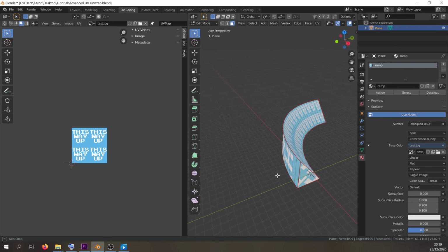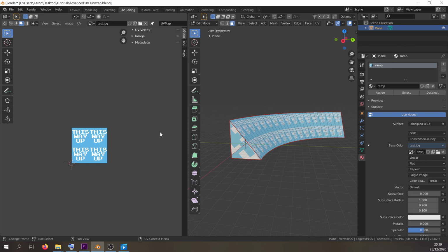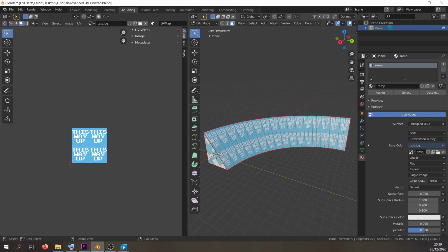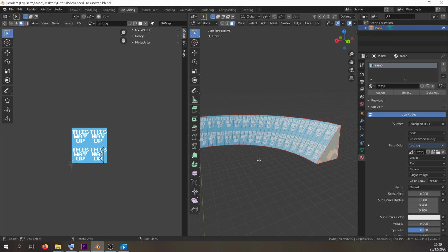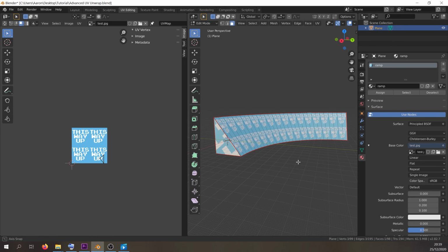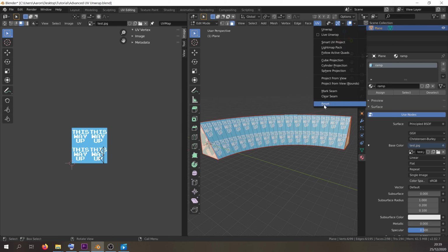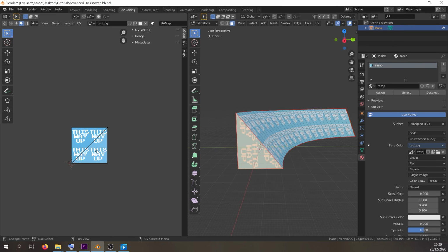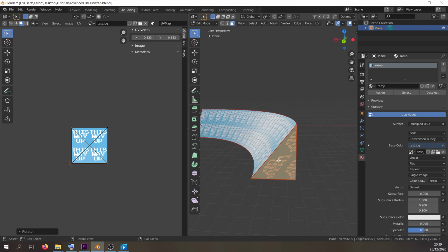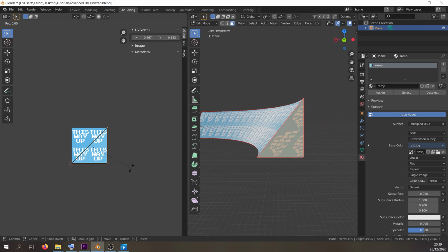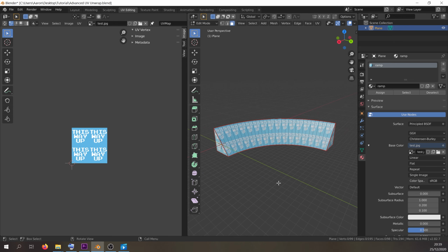You do the rest for the back and the bottom. The only thing different is we do the same method for the edges as we did in our simpler version. So we just select the triangular faces here, push UV and then reset. And then we just rotate these in the direction we need them to be. For these faces, you might notice if you do rotate, you can have it the right way up, but this vertex in the corner here needs to be moved over to this corner. And there we go. So that's how you create more advanced UV shapes.